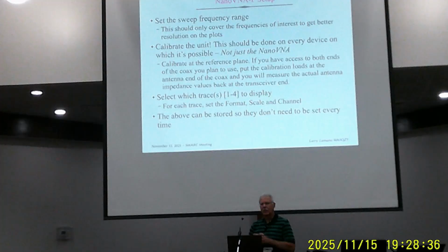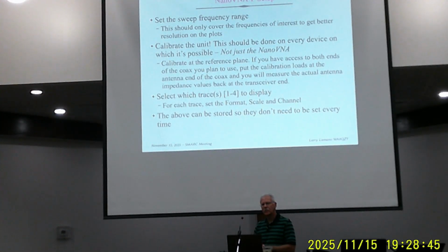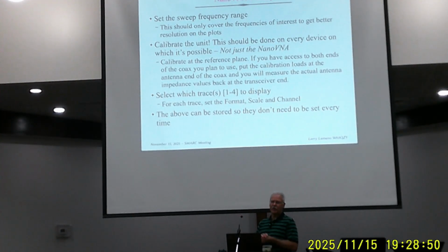Yeah, Jim? Let's say I'm out of my house, and I'm trying to pull one megahertz. Unhook that coax, hook it up to that machine. What's it going to do? It'll measure what's at the balun. I mean, it won't measure really the antenna. It'll measure the antenna through the balun, but it just measures wherever you've calibrated it. That point is what it'll measure. So if you had like a 200 ohm antenna with a 4-to-1 balun, it should measure 50 ohms, if that's kind of what you're asking.